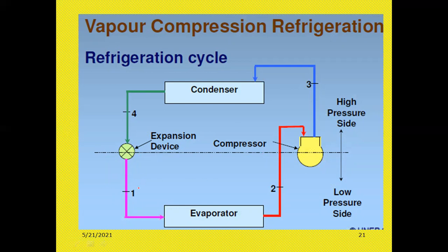So first draw the box for the evaporator, later draw the compressor where the refrigerant gets compressed. It should be at some place at the height of the evaporator, right? You have a compressor with a lower pressure side and an upper pressure side.